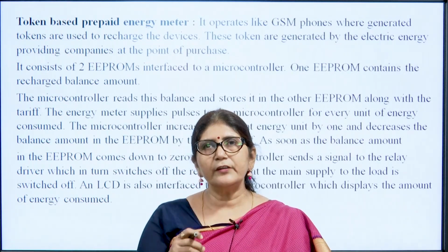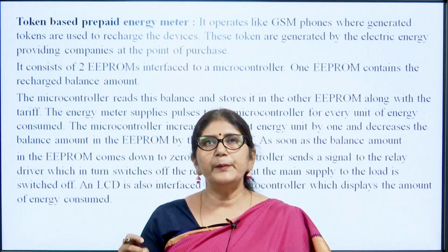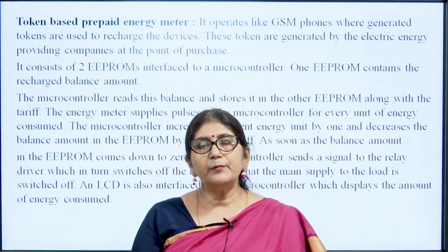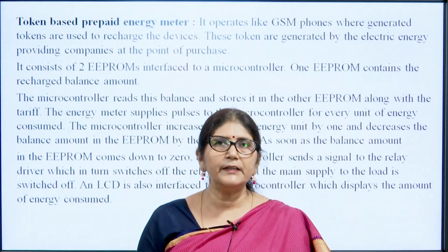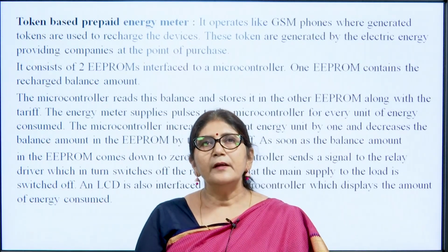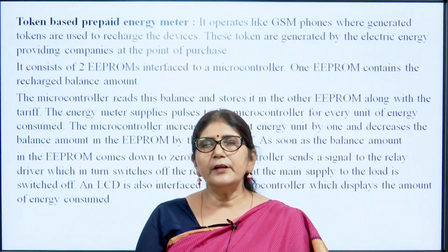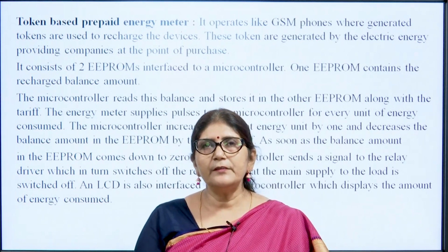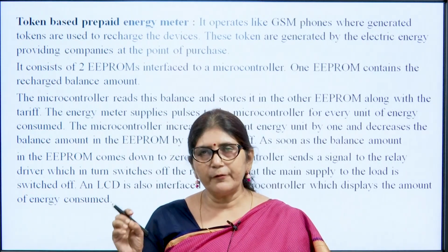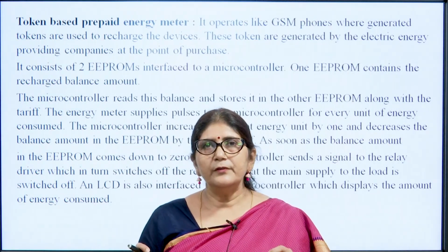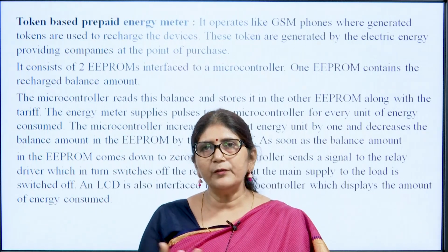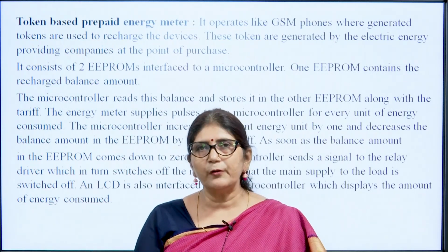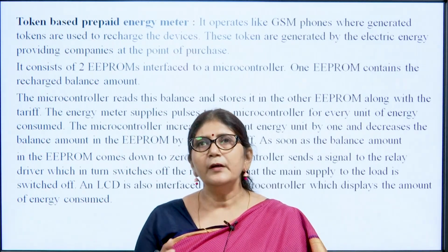EEPROM means electrically erasable programmable ROM, and the microcontroller reads the balance and stores it in another EEPROM along with the tariff. Energy supplies a pulse to the microcontroller for every unit consumed, so that the microcontroller increases the energy unit by 1 and decreases the balance amount in the EEPROM by 1.